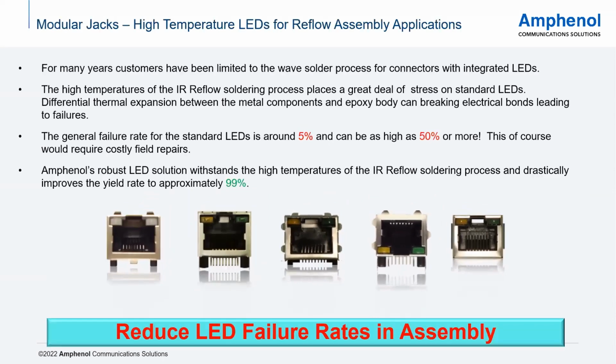One important thing here is that we have a very unique design for the high temperature LEDs. Whenever the customer is requesting an IR reflow process and wants the LEDs to be compatible with high temperature, we have specifically designed a high temperature LED, which gives you a reliability of around 99%. The general failure rate of LEDs in the IR reflow can be as low as 5%, as high as 50% if we use a standard LED. And that is the reason why we offer a specific LED for the high temp IR reflow applications.